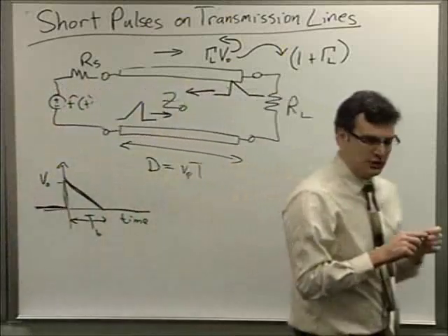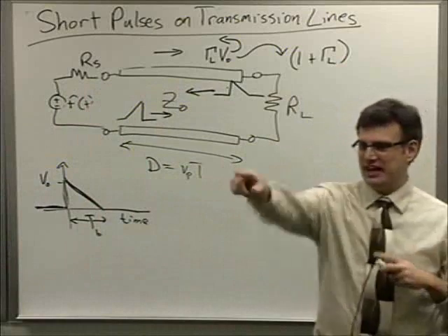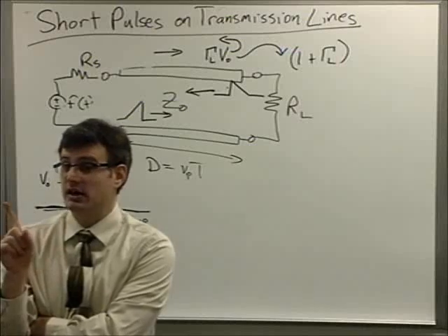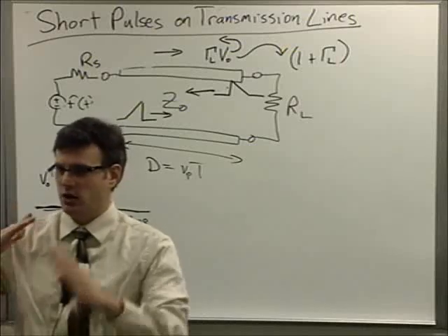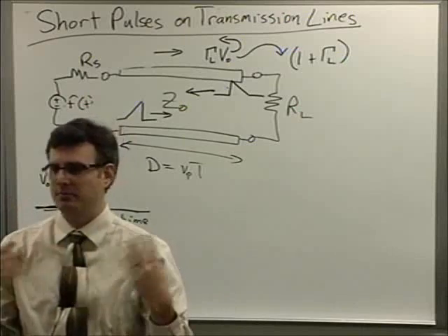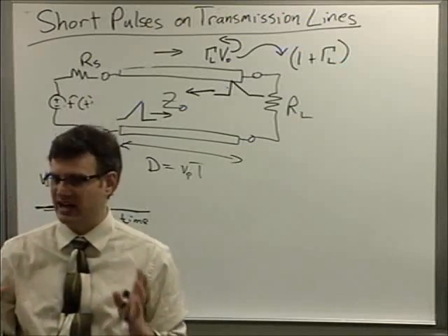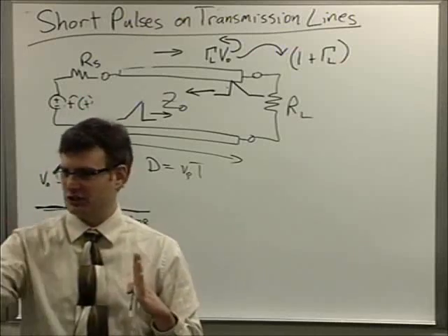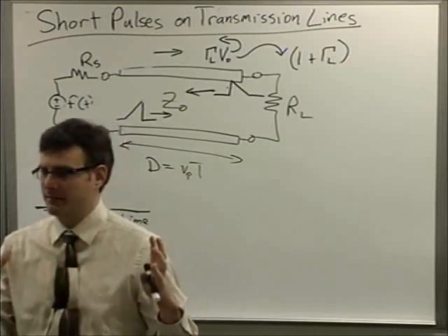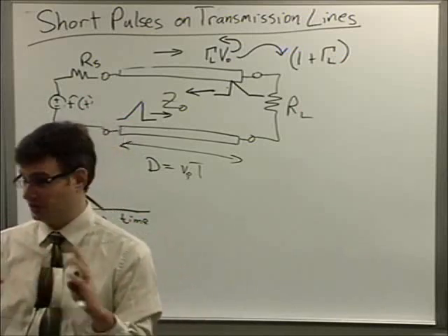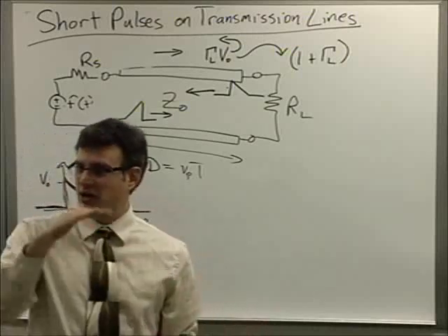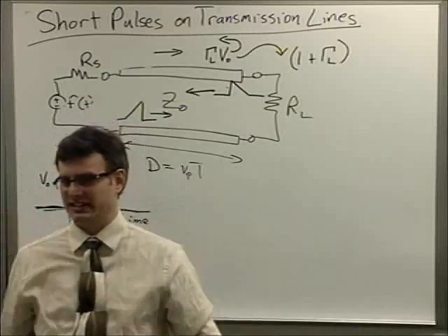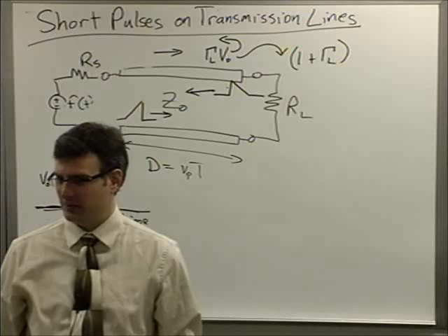Now, any questions before we look at some graphs? Yeah, go ahead. The signal doesn't remain the same. That's right. Well, the thing is, these lossless transmission lines are nice because the shape of the pulse is preserved. There's no amplitude distorting attribute on the line itself. The only thing that changes is that at the abrupt interfaces we have reflection coefficients, and a portion of all of that pulse will reflect, and a portion of all of that pulse with the same shape will transmit. And so you'll find each reflection dies off, gets smaller and smaller, and after so many transit times you probably ignore anything left on the line. But the shape will always be the same.